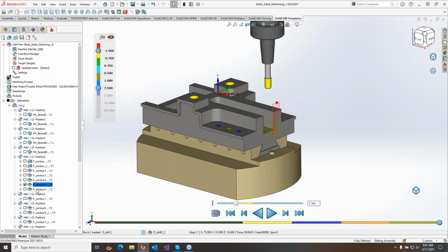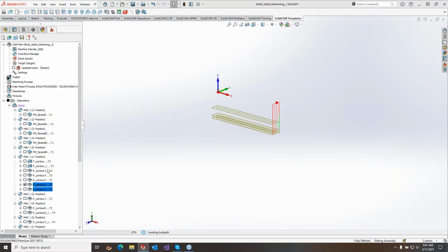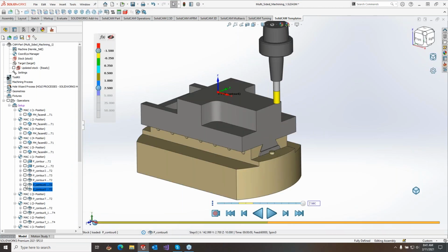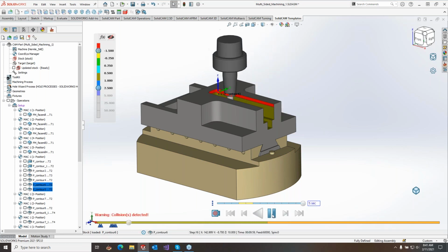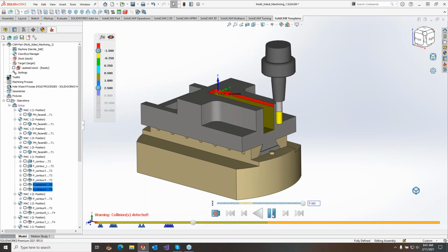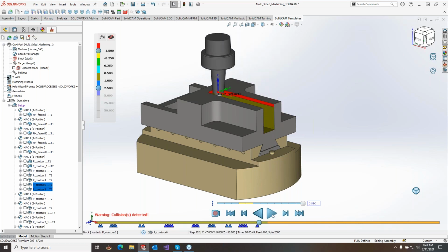So we just reordered these operations while the simulation was open and there was no errors. So I'm gonna relaunch. Of course, we need to relaunch the simulation to get the new timing of the order of the operation. So we relaunch it, and I'll still stick with machine time mode and equal playback, and then we'll play it.